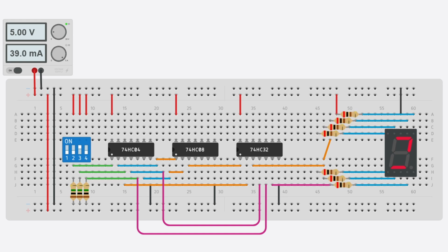If we wanted to display a 2, for example, we would turn on only our B input, which has a weight of 2, and we can see that the C segment turns off, just as we would expect. And again, we're going to cycle through the whole combination of numbers later, but for now, we'll move on to segment E, as we've already connected segment D because it shares the same logic as segment A.